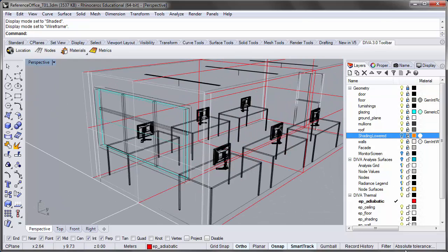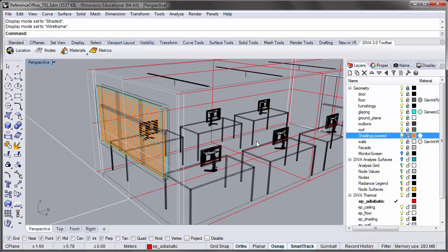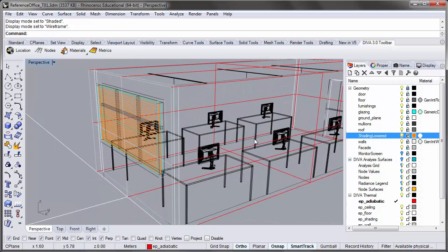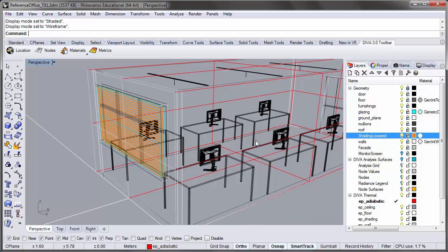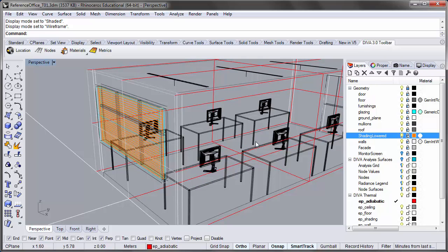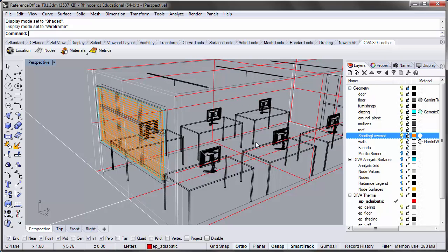The daylighting geometry has a layer for dynamic shading that is modeled explicitly in Rhino. For the thermal model, we don't actually have to model these blinds. The shading is going to be sent to EnergyPlus as a dynamic shading device, and its presence in the thermal model will be as an exterior blind that is not explicitly modeled in Rhino, that will be scheduled according to the shading control groups that we ran in the previous tutorial.